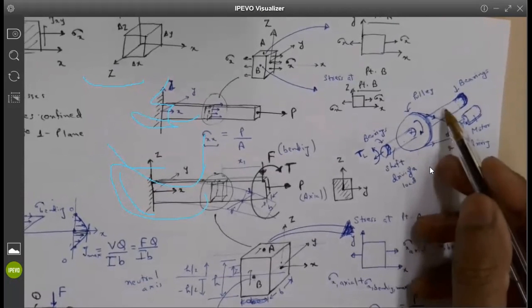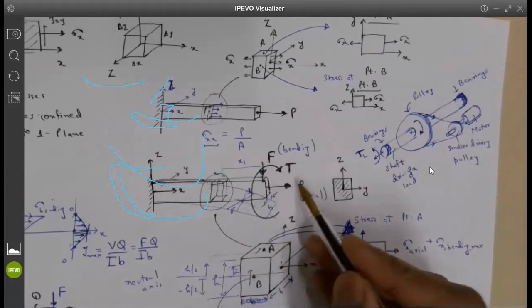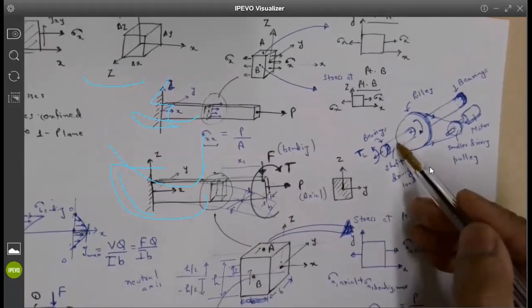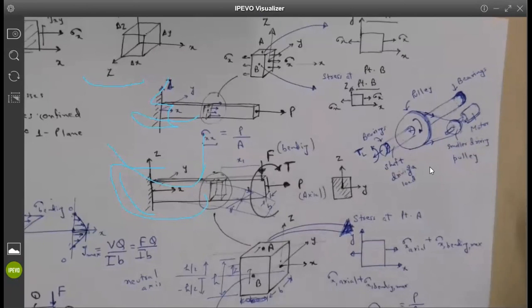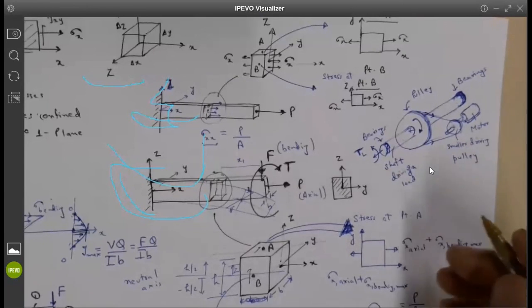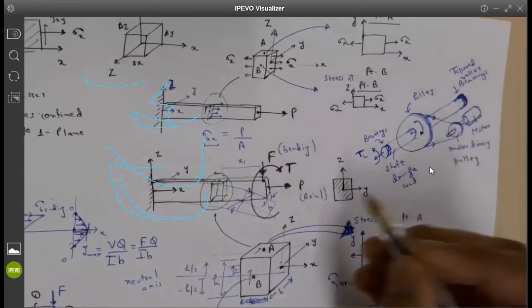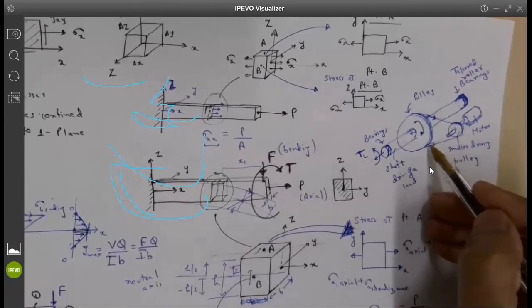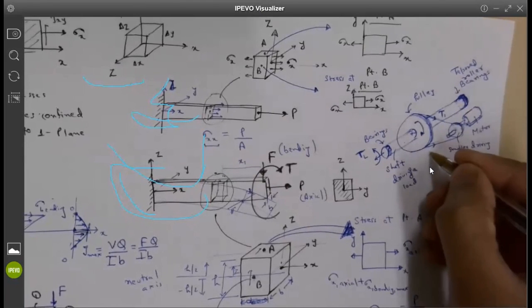So this specific situation is exactly the case we are learning. So you have the axial load. The axial load may be due to a helical gear mounted on the shaft, which gives an axial load that is transmitted to the bearings. In that case, the bearings have to be not simple ball bearings or roller bearings, but tapered roller bearings to carry the axial load. Then you have the axial load, you have the twisting, and you have the bending load, because the pulley is getting stretched by the tensions on the wires or the ropes.